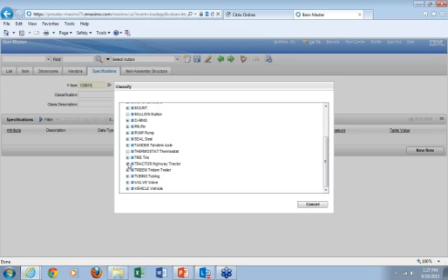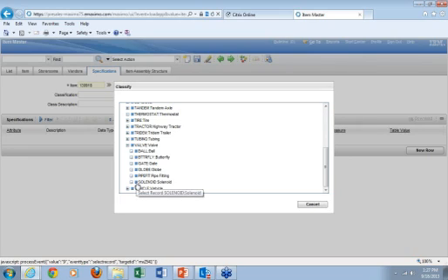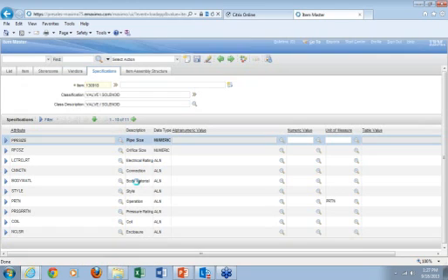And as in any other application in Maximo, you have the little plus signs to expand your selection. So let's drop down a little more. And then I have to click on the little blue box to select the actual valve. I'll click on solenoid. Now you see the classification shows up. It's valve, solenoid, and here's all the attributes.